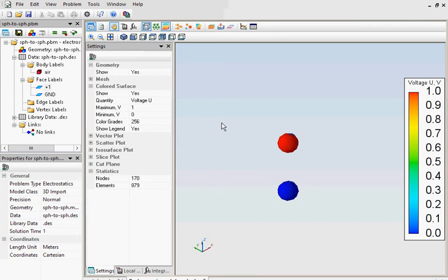In most real problems the field distribution is non-uniform. QuickField utilizes the finite element mesh method to compute the field distribution. The space is divided into elements. Inside each element, the potential is considered to be linear.